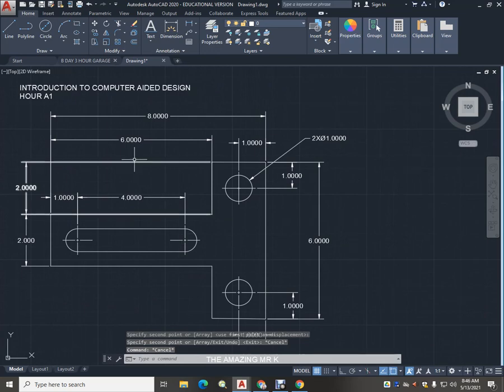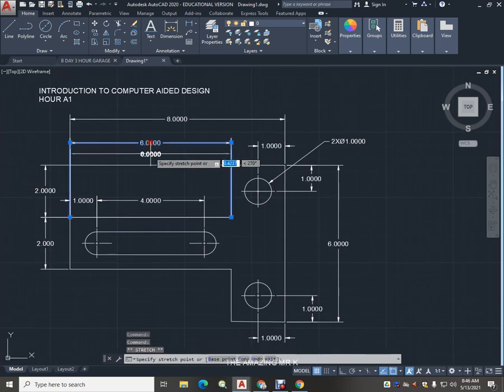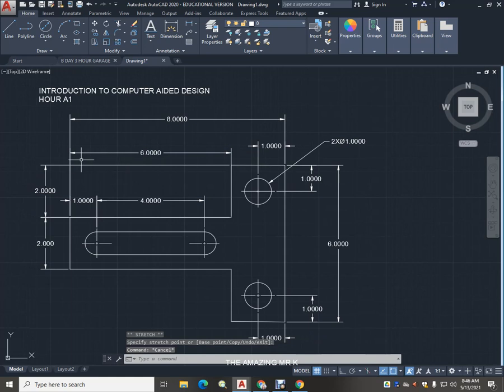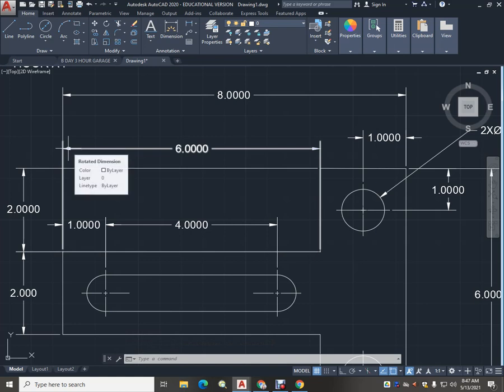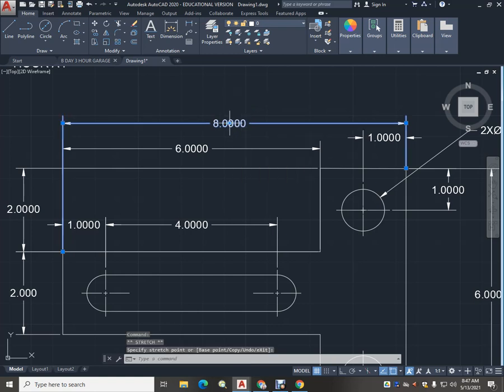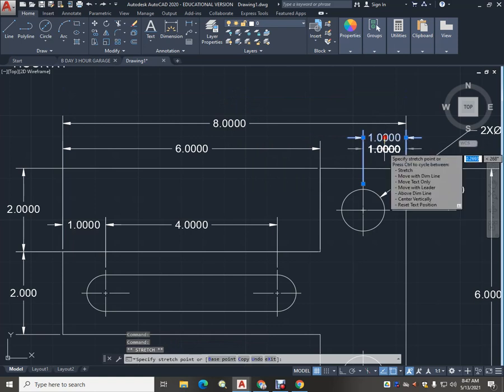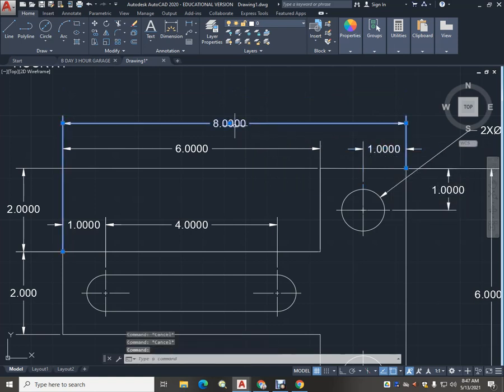I also could consolidate and move some of these dimensions down. We don't necessarily need to have so much room. If we were to look at old school dimensioning, from here to here, the first dimension, the old book says that we have to have that at least a minimum of 3/8 inch away from the part, and then consecutive dimensions beyond that should be 1/8. Should be 1/4 away from the other drawing. So we can push this smaller.